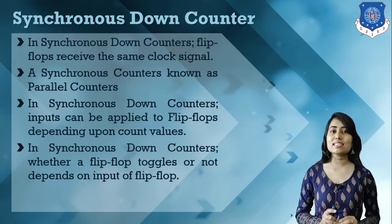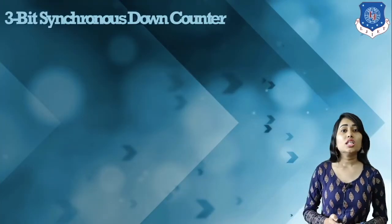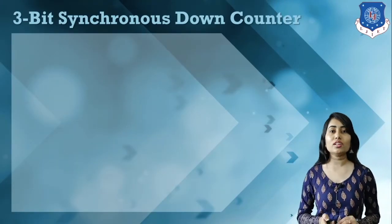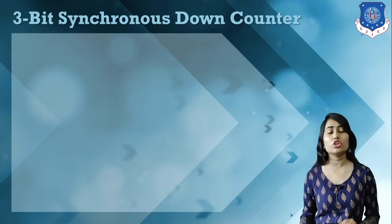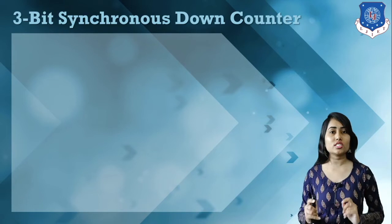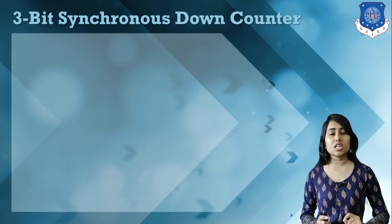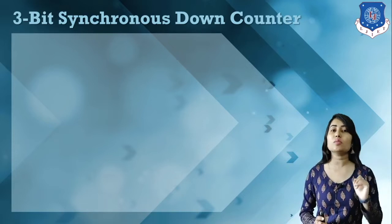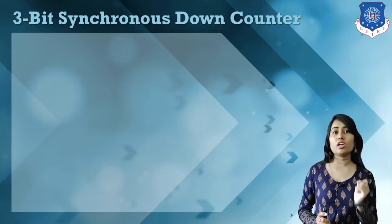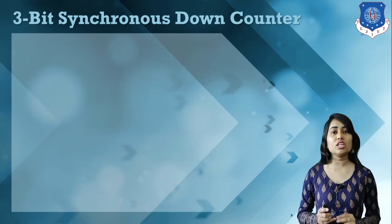So let's discuss the synchronous down counter with an example. Here we want to design a 3-bit synchronous down counter. To design it, we have to use 3 flip-flops, right? Using these 3 flip-flops, we can count a total of 2 raised to 3, that is 8 possible values, starting from 7, 6, 5 down to 0.